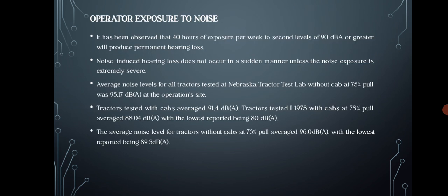Operator exposed to noise. It has been observed that 40 hours of exposure per week to a sound level of 90 decibel or greater will produce permanent hearing loss. Noise induced hearing loss does not occur in a sudden manner unless the sound exposure is extremely severe.